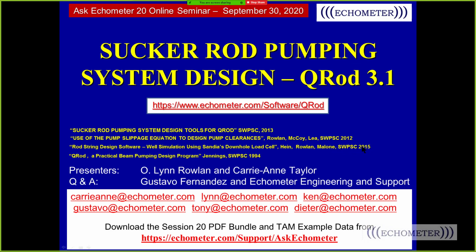The paper referenced here from 2015, Norm Hine, myself, and Scott Malone, we compared the different design programs that were on the market, QRod to the other 2 that you paid money for. We compared them to the surface measured horseshoe load cell data on 6 wells, and QRod matched the best of all of them. We also have a couple of papers here. This one paper we published in 2012 is on slippage. QRod has a slippage equation that we'll talk about, and we've added some new tools, and we'll talk about those tools.